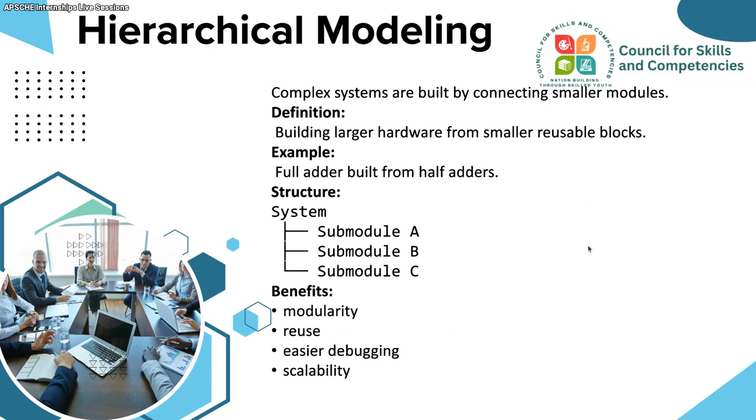Next, for the second half adder, this is an S1 line that I want to connect to the A port. The sum 1 line, I want to connect it to the A port, correct? Because already this S1 we connected to the sum of the first adder.